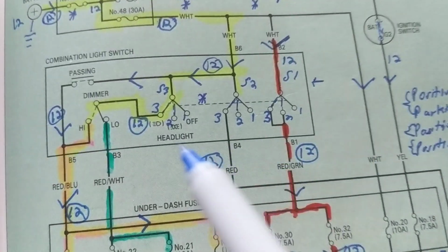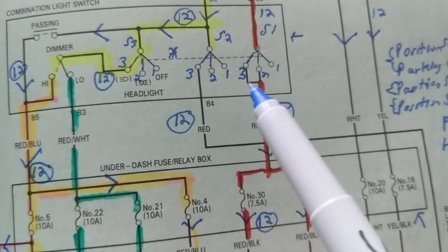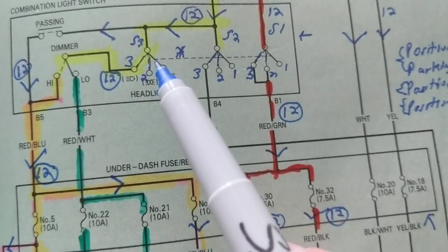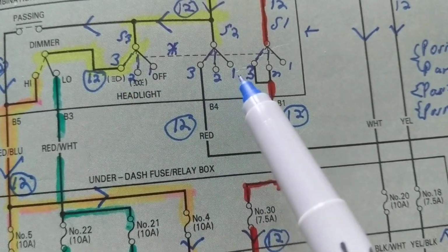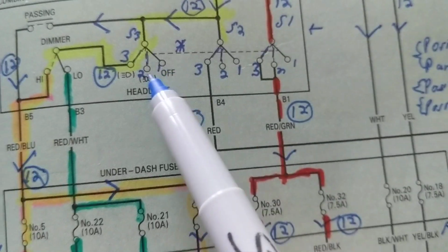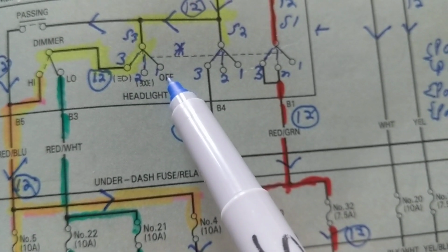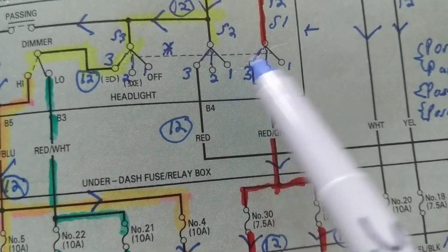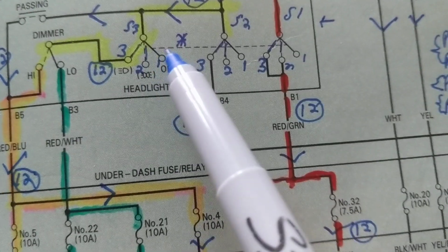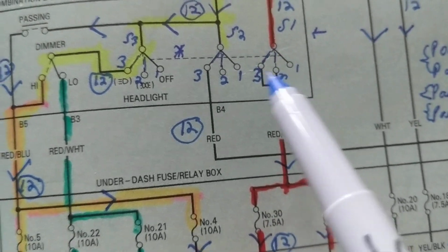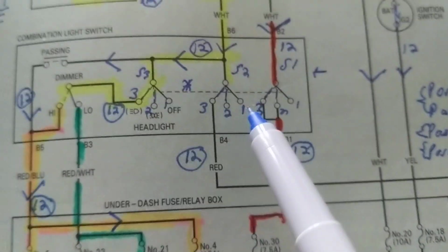This is the important detail. Like we said before, when you see the dotted line, that means they are ganged together. Remember, I used the terminology Siamese twins. That means when this part of the switch is switched, this one, and I labeled it to make it easier. I called this one 1, this one 2, this one 3. Whenever I put this part of the switch to, let's say, terminal 1, this will go to terminal 1, this will go to terminal 1, all at the same time. When I put this switch to terminal 2, this will go to terminal 2, this will go to terminal 2. When I put this to terminal 3, this will go to terminal 3, this will go to terminal 3 simultaneously, together at the same time.